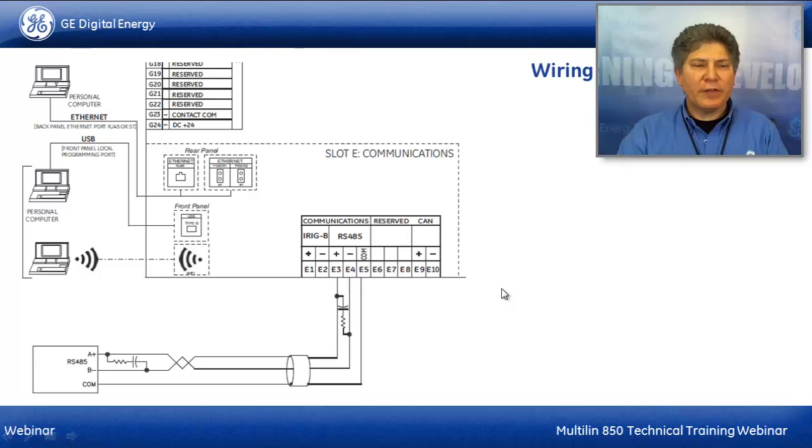The RS-485 communications. We have a single connection for RS-485, with terminators at both ends. These are typically a 100 ohm resistor, quarter watt, in series with a 1 nanofarad 50 volt DC ceramic cap. So this is eliminating the ringing in the communications. It should be grounded at one end only to avoid any ground loops and intermittent communications.